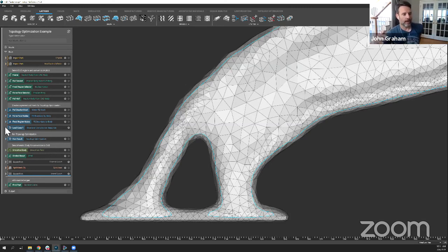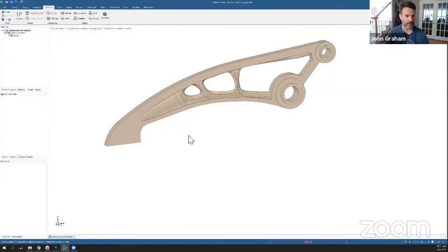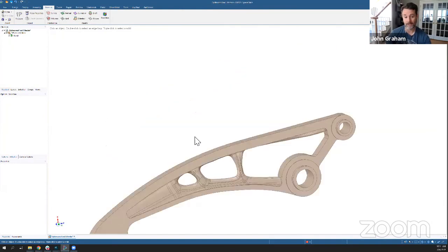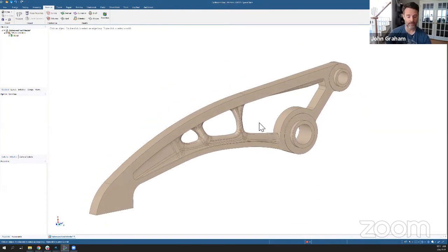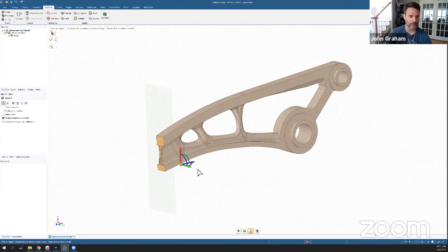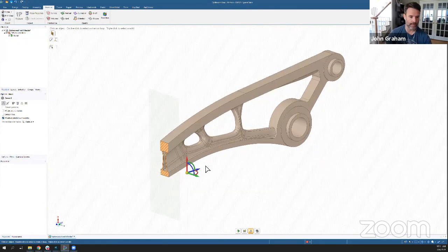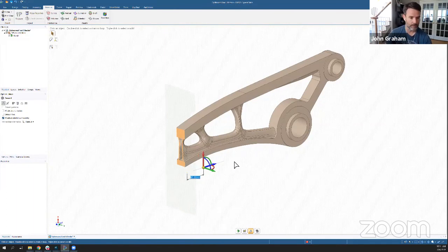And we found for now, it's just a little easier to take those two distinct boundary representations, the outside and the inside, bring those separately into a CAD tool and merge it all together. And that's exactly what I've done. So I basically took three bodies here: the frame, the inside surfaces, and the outside ones. And I've merged them all into one. And of course, you could do this in any of your favorite CAD tools. I happen to know ANSYS SpaceClaim a little better than the others, so I brought this in here and in no time was able to merge these together.